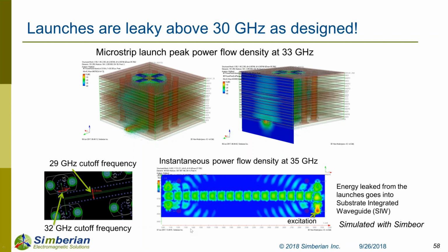One of the lessons learned is you have to really stitch everything together and look at the signal as a wave. If there's an opening that's large enough, the signal is going to escape. Also on the board, I measured, for example, traces that were 6 inches away, completely on the other side of the board, and there were plenty of stitching vias across the whole board. At the frequency where we had the launch localization breakdown, around 33 gigahertz, you could see a huge increase in coupling. At some places it was like minus 26 dB of coupling, and these traces are 15 centimeters far away. So you get signals traveling across this parallel plate cavity. If you do any antenna design, this can ruin your day. So launch localization is really important.